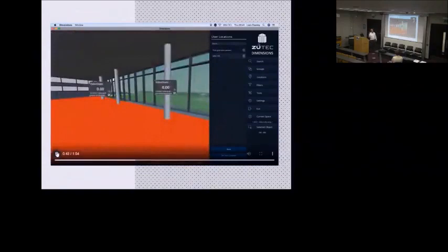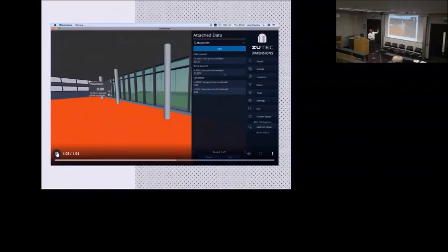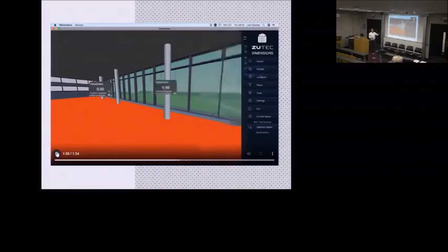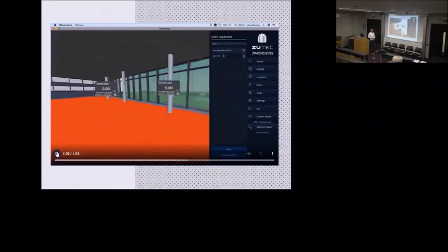This is the research room upstairs, I think. The valve state will be for AC units above the ceiling. We've got temperatures, all in this same area. Very easy, and this is real time. See how fast you can move around. These are the different data points that are available, the different information in that room. So you're loading all of that live directly through the BEMSERVER from the Cylon sensors.